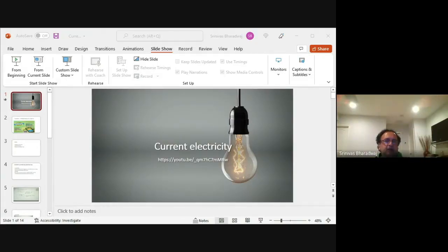He starts here: plus 12, negative to positive, minus I3 times 2. And I3 is I1 minus I2. So plus 12 minus 2 times (I1 minus I2) minus 2 times I1 equals 0. Similarly, for this one, minus 6 plus minus I2 times 2. And this one is going to be plus I3 times 2.